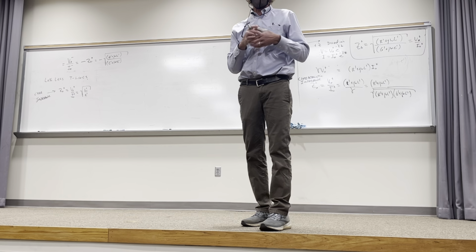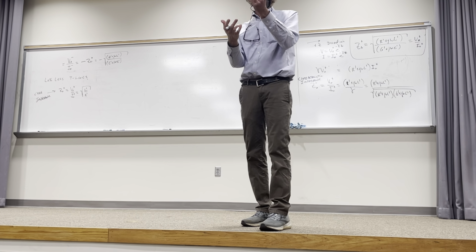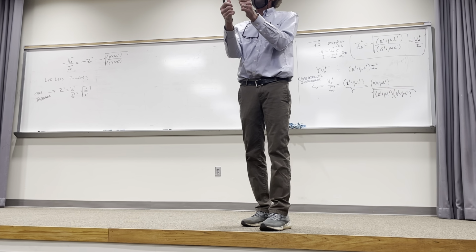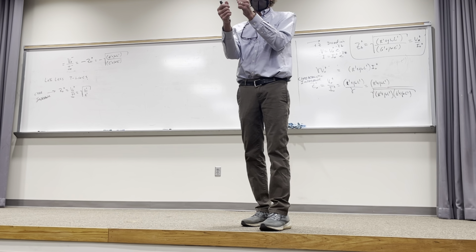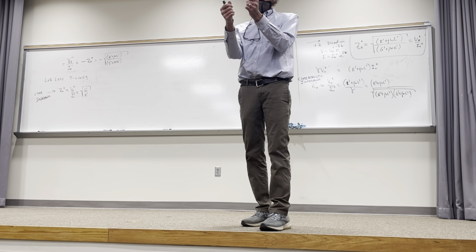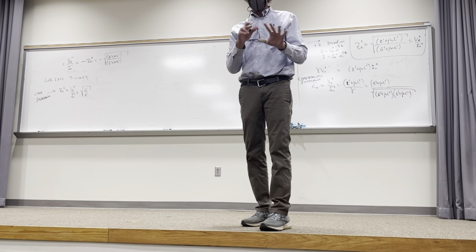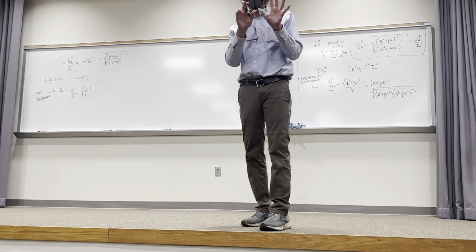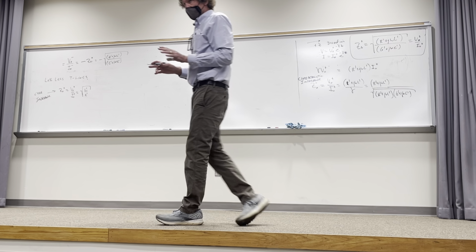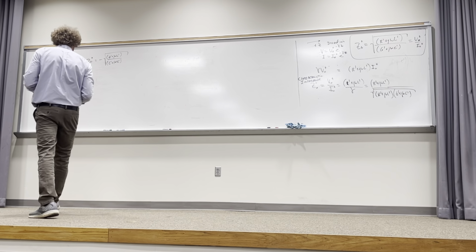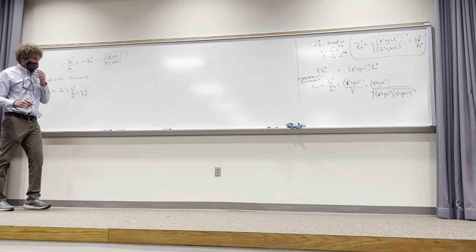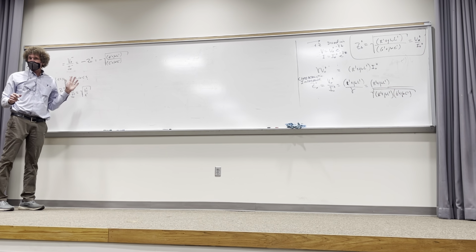Like 8 ohm speakers mean that the speaker itself is 8 ohms, and if you ever put a battery across a speaker coil, you'll fry it because it's not 8 ohms, all right? What it has to do with is the characteristic impedance of that speaker coil at a certain frequency. I'm not going to go there, but there are a lot of things that happen based on false and foolish assumptions. Now, with that in mind, what I just said, that's the characteristic impedance of the line.